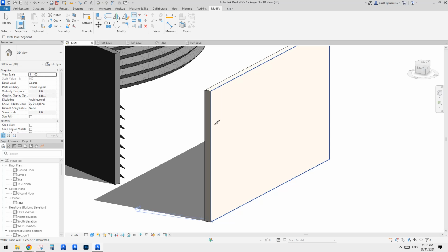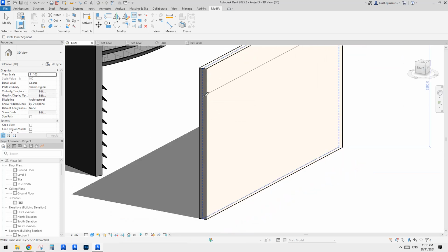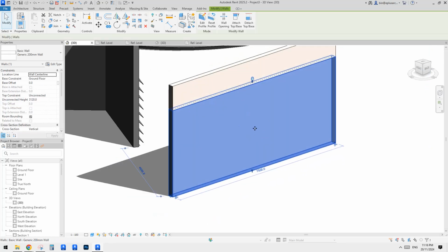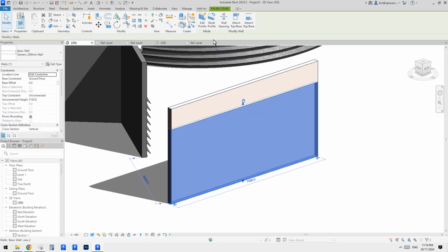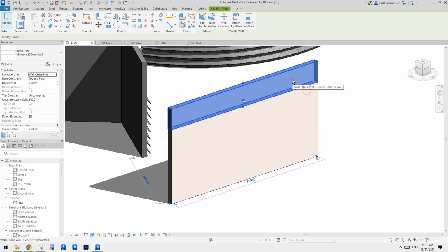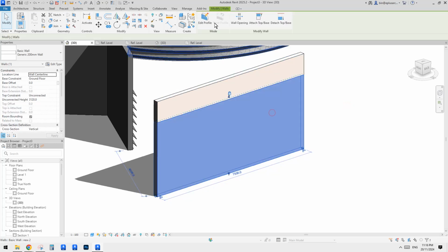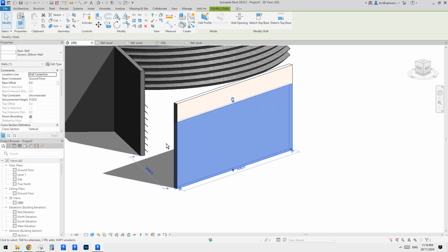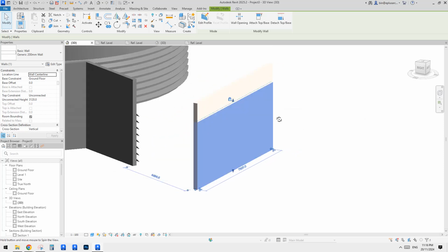We can always split a wall, so click on the side of the wall. Okay, so we have the base as a wall. We don't need to touch this wall or edit the profile, anything, right? Oh, why is it reset profile? Did I just click on that? Not sure. Maybe I'll click on reset for now. We should have edit profile on the base, because the base is always rectangular, right? So it's a base and a top, and that's it. We don't need to edit profile.